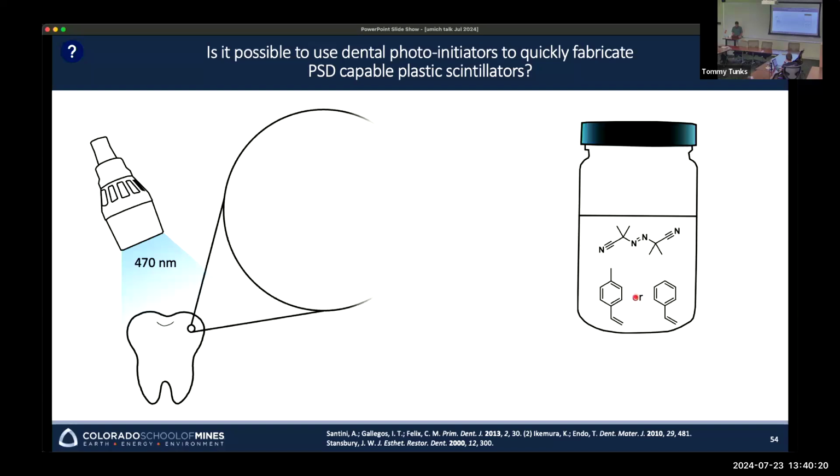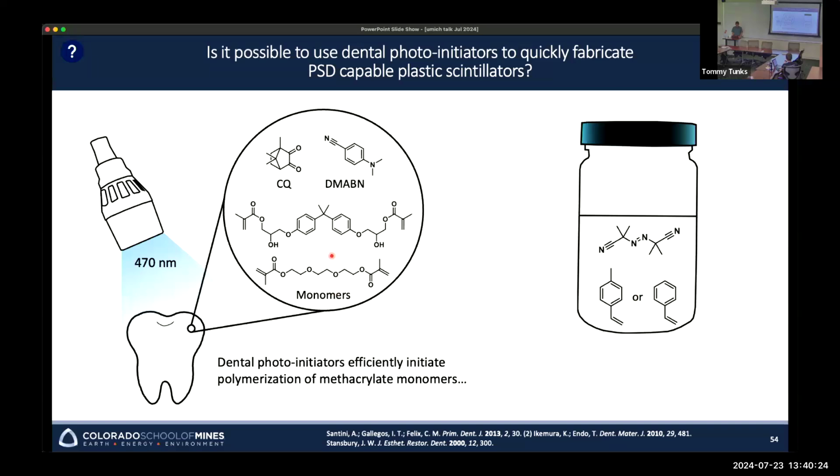So you're basically taking a monomer, cross-linkers, some kind of photo initiator, and mixing it with this silica or zirconia, and then you're polymerizing everything in an environment with oxygen, with moisture, and doing it super fast so that it can cure in your mouth. And in reality, these photons can only penetrate a certain distance. So when they do these dental fillings, they usually have to do it in a series of like 4 or 5 steps. They put down a thin layer, they zap it, they put down a thin layer, they zap it, because if they put it too thick, photons can only reach a certain penetration depth, and that means things are not curing down below. But this is exactly the chemistry that we started with. We use these same types of photo initiators that they use in the dental composites.